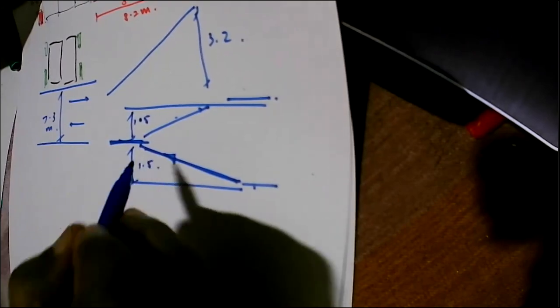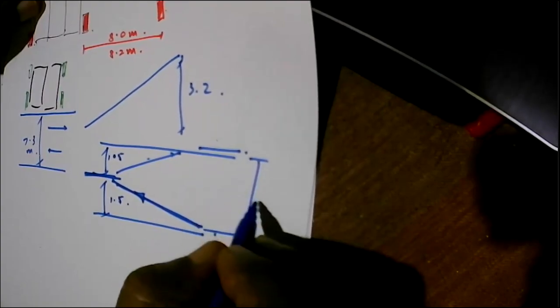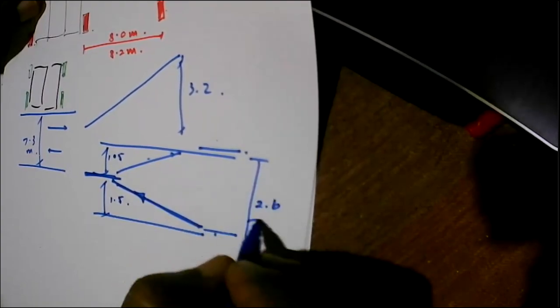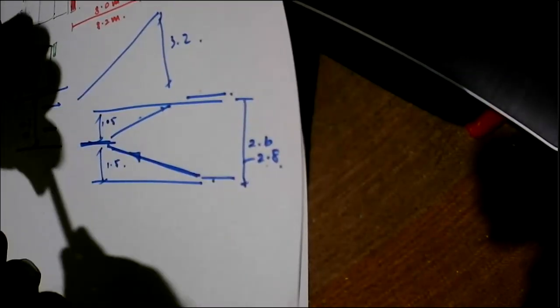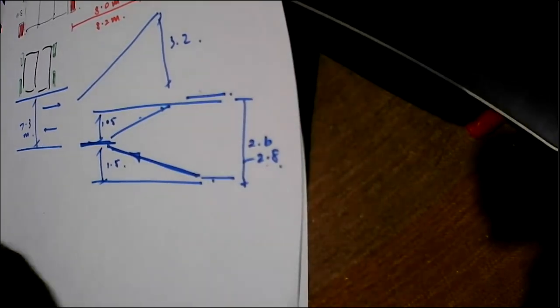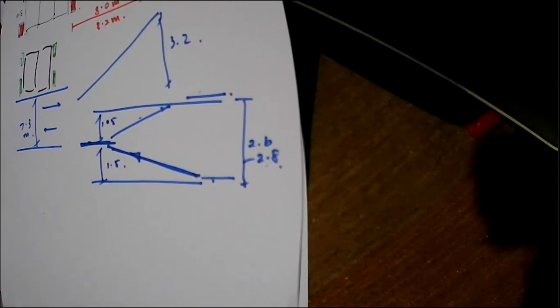But in car parking floors, generally we keep the floor to floor height somewhere around 2.6 to 2.8 meters, because greater heights are not necessary. The height of a vehicle is about 2.1 meters maximum. So in the car park areas, you can have heights between 2.4 and above. So to allow for structural elements and so on, you might end up with something like 2.6 to 2.8 meters for the car park areas.